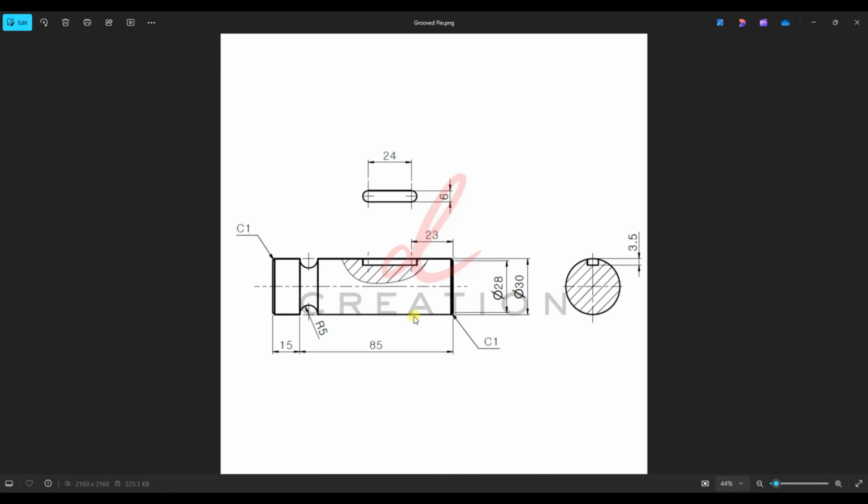So today I'm going to teach you the easiest way to create a straight or cylindrical object like this within a single sketch. When we look at it, we have the cylinder pin with a circular cut over here, and then they use the slot cut over here. First of all, we are going to forget about the slot. We are going to create this area and then use the Revolve feature to create the whole pin within one sketch, and then finally we are going to use the reference plane to create a plane over this, cut the slot, and then give the chamfer over here.